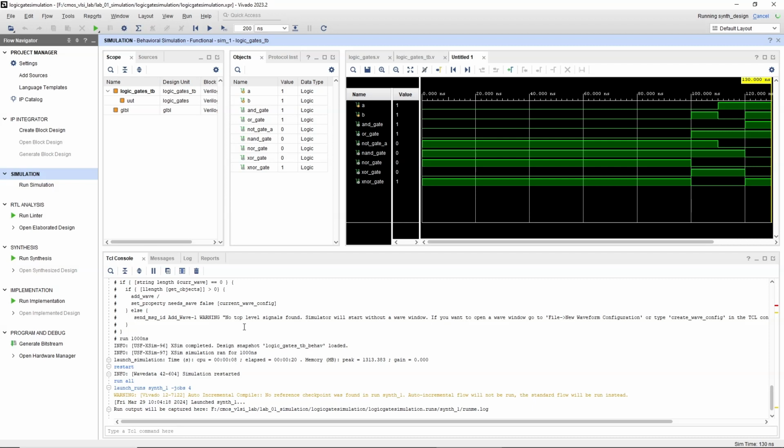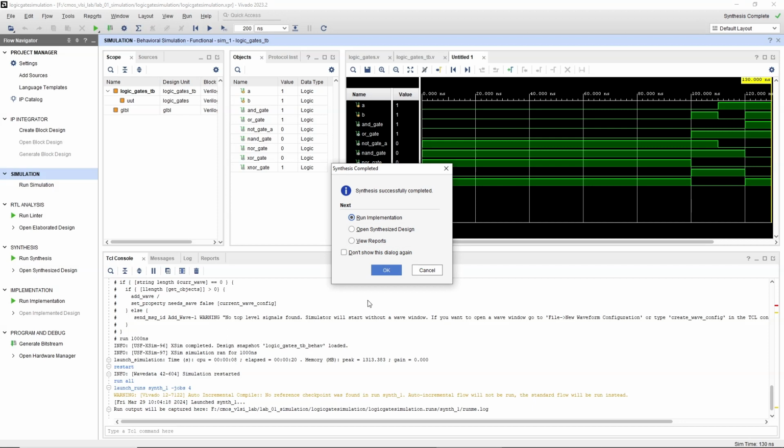You'll receive detailed reports on how much of the FPGA's resources your design will use, guiding possible design adjustments. After synthesis, you're provided with a comprehensive report that details optimization results and performance metrics. This critical step prepares your project for the subsequent phases of FPGA development, like placement and routing, moving you closer to a finalized design. After successful synthesis, the user is prompted to run implementation. Click on OK to proceed.